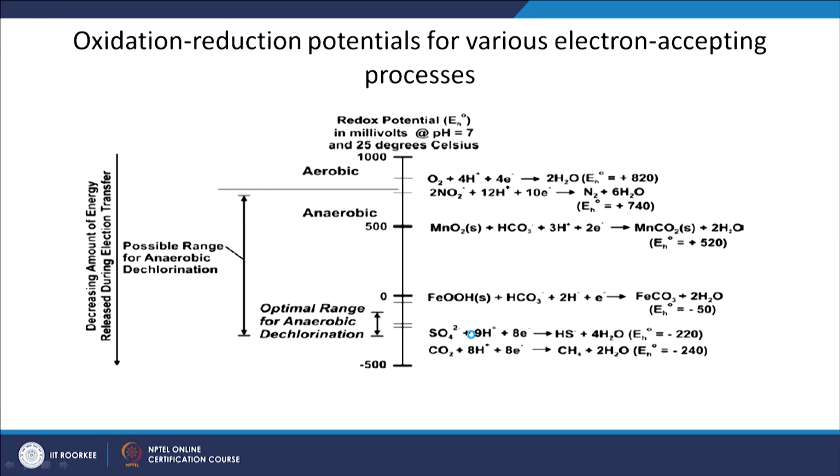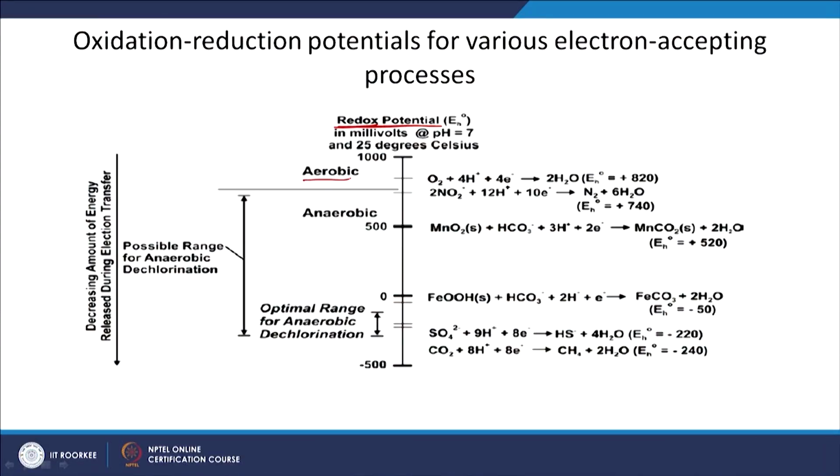So in this case, to be able to understand whether it is feasible or not, we have the relevant graph here. Here I have the redox potential. In one of the earlier cases when we looked at zero valent iron, we looked at cases where it would work only as a reducing agent, a second case where processes such as adsorption and reduction go hand in hand, and one case where only sorption would be feasible. So how do I know whether a relevant compound can be reduced by zero valent iron, or in which cases will a zero valent iron based PRB work well? Obviously, what are some of the ranges in which it would not work well? When you have oxygen here.